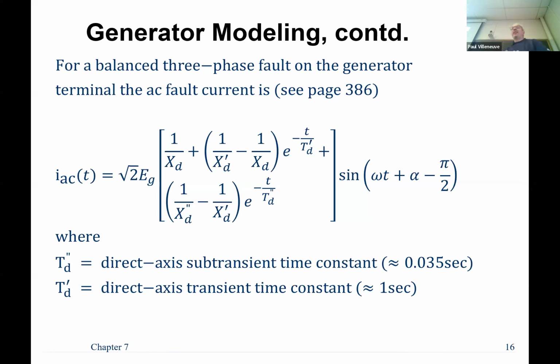Well, if you go with 1 cycle breakers, normally the standard is like 3 to 5 cycle, but if you get 1 cycle breakers and very, very fast acting protection schemes, you can trip much faster, and now you're starting to encroach into perhaps the subtransient time. So now the breakers have to be much heavier duty. But again, there's advantages to that because you have a more stable system.